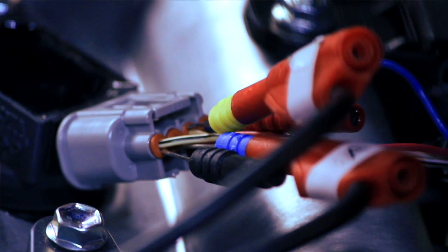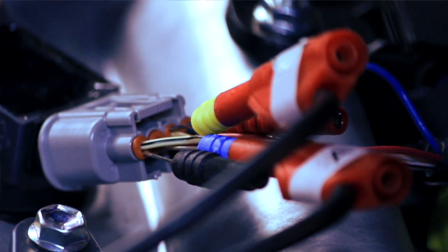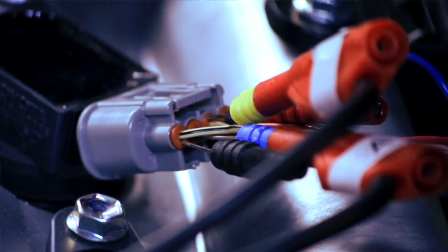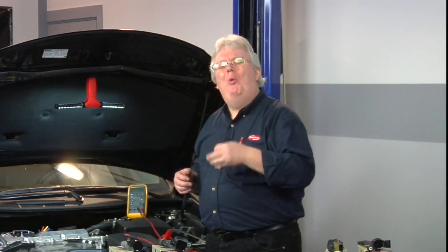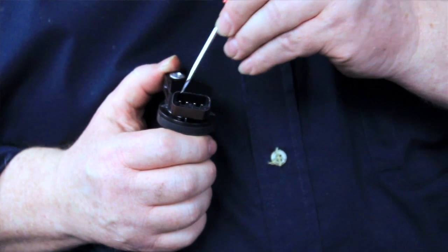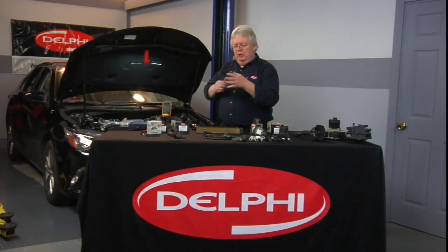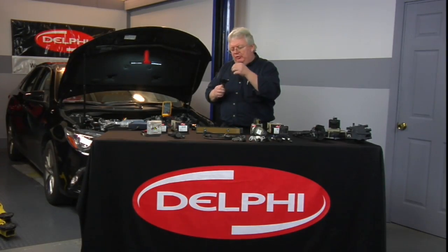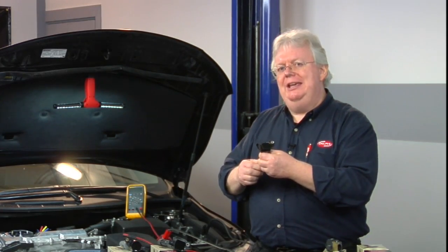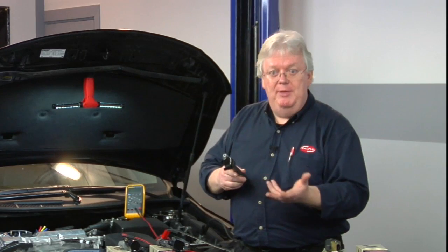So I went ahead and set up for back probing the connector. Terminals A, B, C, and D, a 4-terminal type coil, meaning that the drivers that control the solenoid, or the winding I should say, for the primary side of the coil, those drivers are buried inside the little coil pack module. So the coil-on-plug module has the transistor that is going to turn the ignition primary circuit on and then turn it off, which is going to then induce the secondary voltage and make our high voltage to our spark plug.